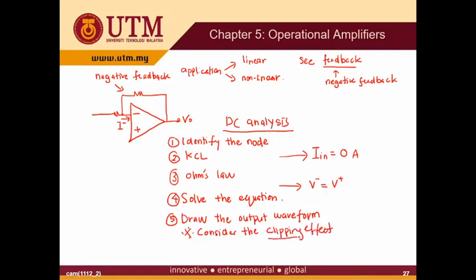Clipping effect is where the output voltage is much larger than the maximum DC supply, or the output voltage is lower than the minimum. In those cases, it will be limited by the DC source.